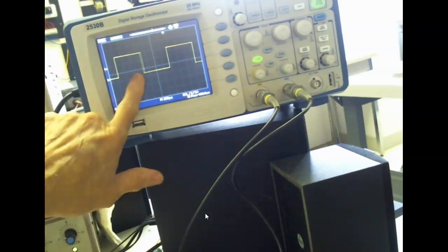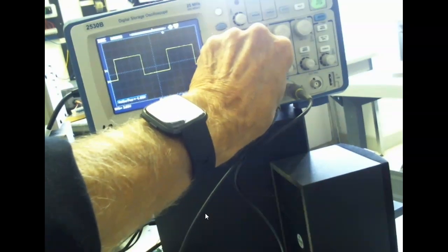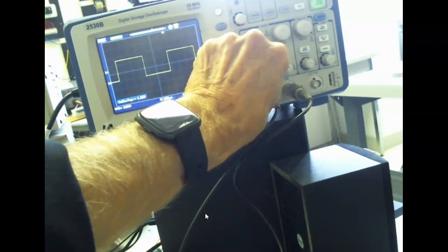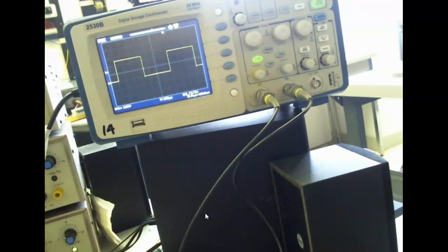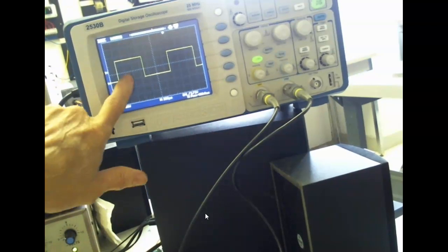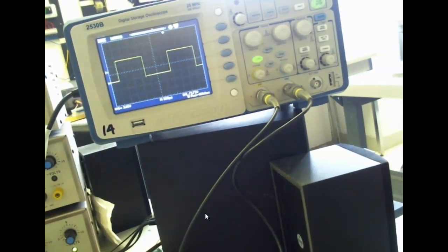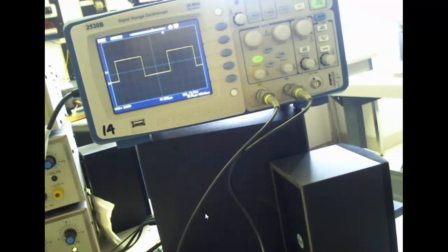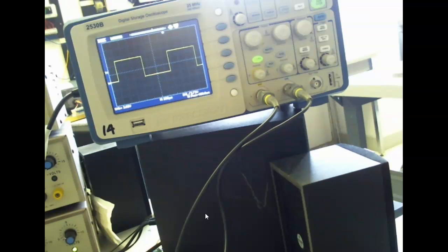And we measure volts this way. To measure volts, I'm going to get my trace on a solid line. We have it on 2 volts per division, so that's 5 volts right there. So this is a 5 volt pulse, right? Everybody okay? Makes sense. So guys, what do I do now? That's the time for one pulse. So what would be the time for a revolution? That's the time for one pulse on this guy. We're trying to figure out how fast this guy here is turning.